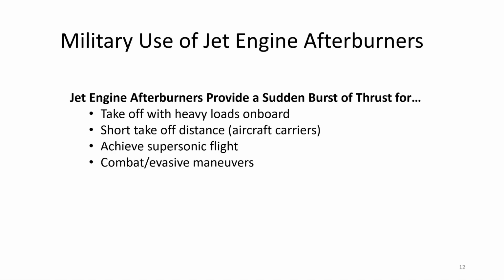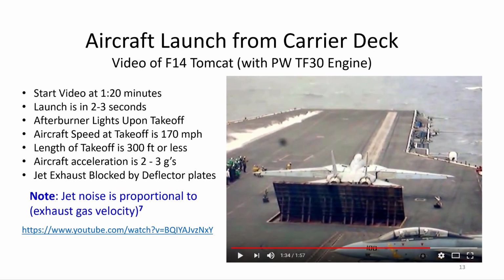Number one, they provide a sudden burst of thrust for takeoff with heavy loads on board, a short takeoff distance, for example, with aircraft carriers, and to achieve supersonic speed, and also evasive and combat maneuvers. That's when these are used. Now what I'd like to do is to show you a video clip of a jet taking off from an aircraft carrier. The launch only takes about 2 or 3 seconds, and the afterburner lights up as soon as we take off, as soon as we get over the edge.